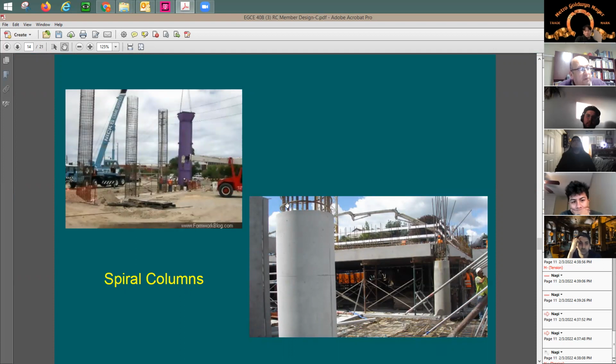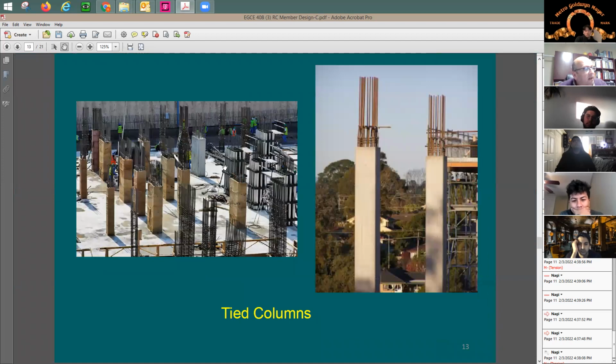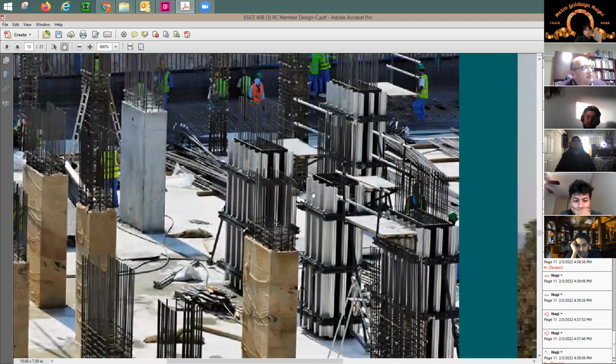This is correct, but we call it here formwork. This is a standard way of calling it. Like in here, look at this. You have the form, which is this black thing around. You see this black sheets, and then you have some members, right, to provide the stiffness of the form. And after they pour the concrete and the concrete is hardened, they release this form. They took it out, and once they take it out, you're gonna end up with a column like this.